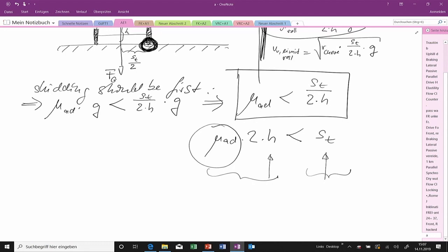Okay? The same is with the car. This roll oscillation is a system property. It can be calculated from the inertia and from the spring rates of the body springs. Yeah? And by the way, the sway bars. But okay, this is not so important to see with all these details. The only thing is, it is able to oscillate, and it has got its own frequency.